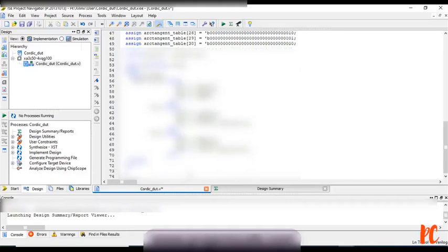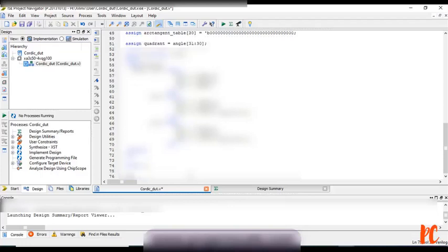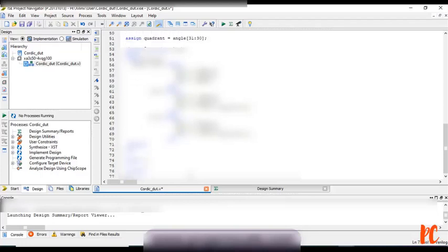Now I need to run with respect to iterations, so I am going to take the keyword genvar i, which will generate a few iterations. Generate, which is again one more keyword, followed by a for loop I am using, initially with i equals 0, ranging with i less than width minus 1, followed by i equals i plus 1. This will create a loop. Again within this loop I am going to write the construct begin.